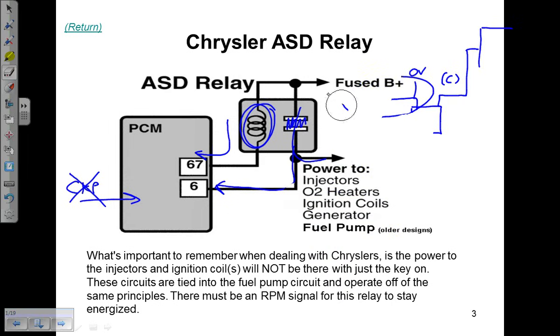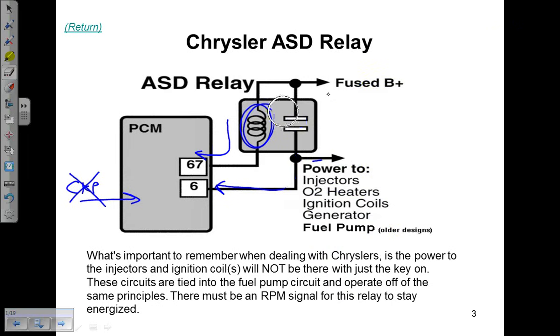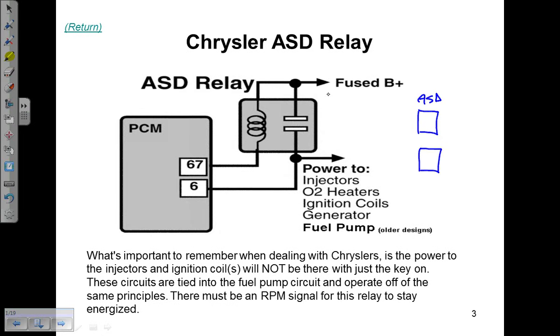On the newer designs, they really didn't change anything. What they did was take the ASD relay and they added a fuel pump relay to it. So you have 2 separate relays, but the thing is, these 2 relays and the control sides of the relays themselves went back to the PCM, and there was only one driver. So yeah, they separated the relays and separated these.